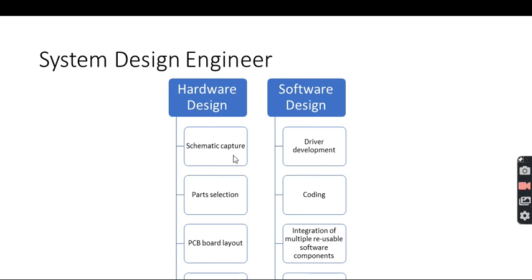Okay, so schematic, first the thing is I have to draw. See, I think you would have used 7805, that it is just a regulator, 7805 regulator. So you know that in that there are three pins. One is input pin, one is output pin, and then one is a ground pin. So these three pins, if I have to use it on a board, for that I have to create that hole for the DIP package. So that schematic is taken care of.